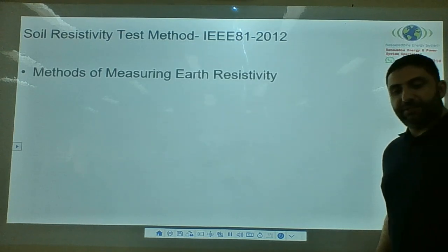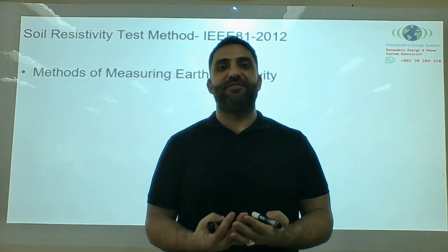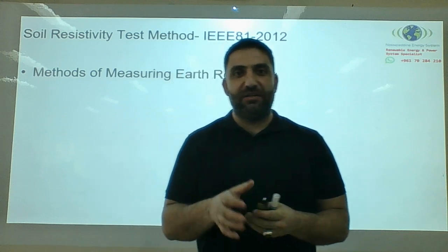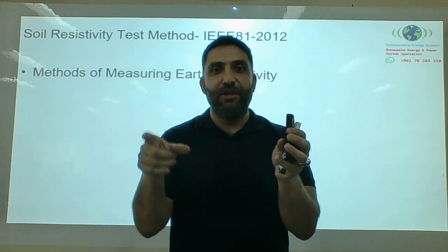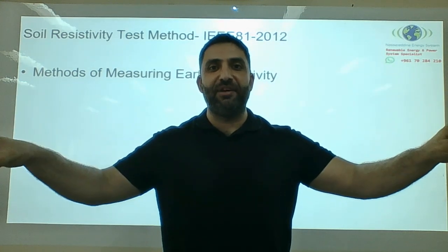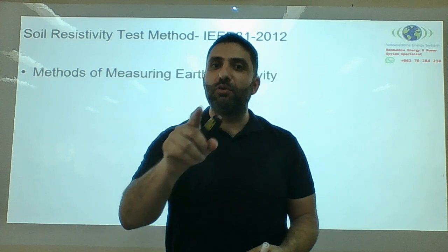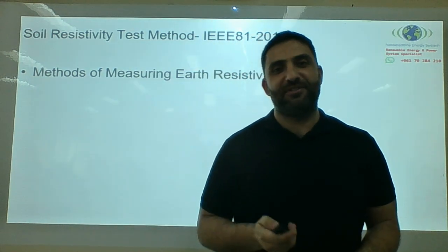Method of measuring. Now, after we establish the importance of our earth grid, I need to measure the process of my earth grid system. I need to measure soil resistivity to be able to determine the size of my grid that gives me low resistance. Next lecture, we will show you how to design an earth grid using the measured soil resistivity.